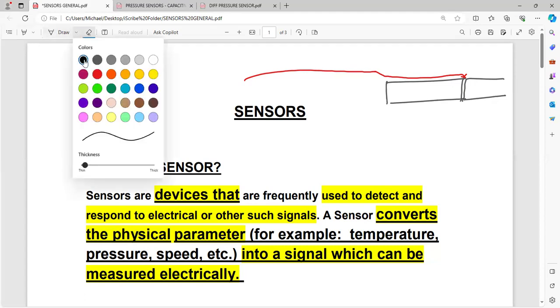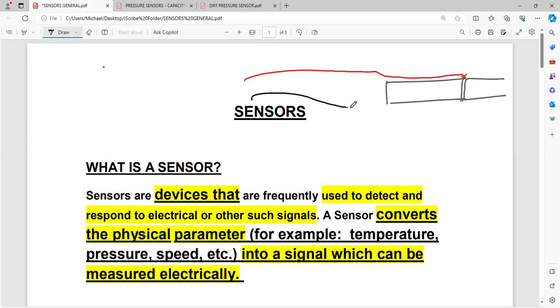He is going to bring that particular black cable all the way from the engine room and connect it to this. You notice that? Anybody on tankers? Yes, sir. So he's going to bring both the red cable and the black cable, connecting the black cable to the pipe. And this one is going to come right from the engine room, just like your red one. In that way, your current is not going to flow through the hull. You are still earthing that pipe.